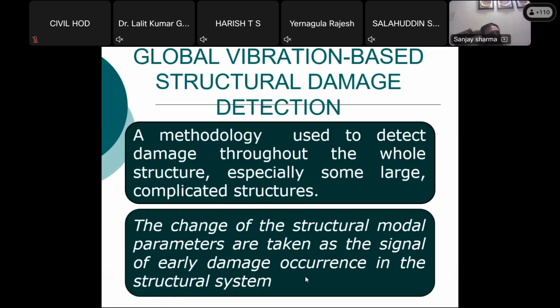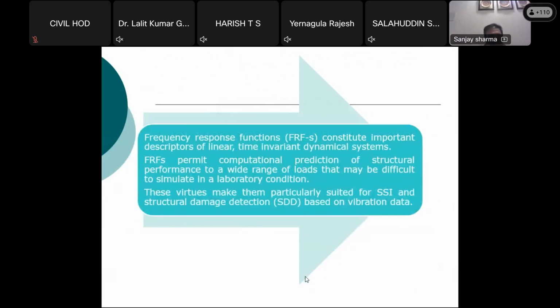So maybe afterwards we may come to this. There is a system called acoustic emission. So what you are doing is putting some sensors in the beam. If some crack or some vibration occurs, it picks up, and then that particular thing can be seen, that okay, how much, if a crack is there, whether it is widening also. So those things are to be monitored, and they will be done like that also.